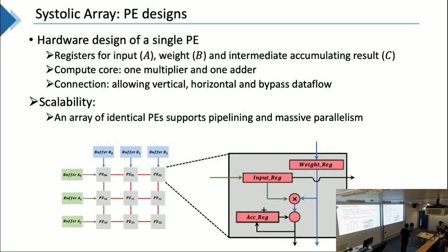And the benefit of this systolic array is the scalability, as I mentioned, because you don't have long interconnects, right? You don't have long wires. They try to squeeze all these compute resources and memory resources in a 2D plane.